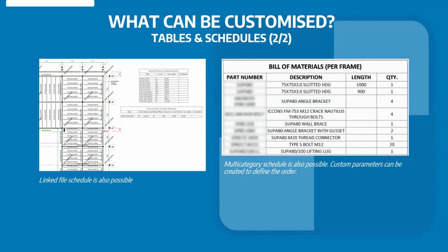Now, one of the downfalls of this system is that if you sort by the type name, Revit will always sort from the numeric value first, and then go to the alphabetic. In this regard, I've been working in different companies, and I created this example for you, where let's say you have an anchor named anchor M12. Then the beam name comes with beam something, then column C with something.